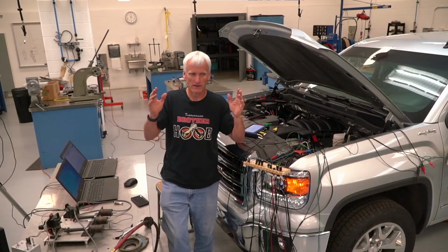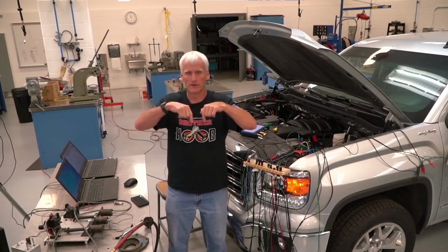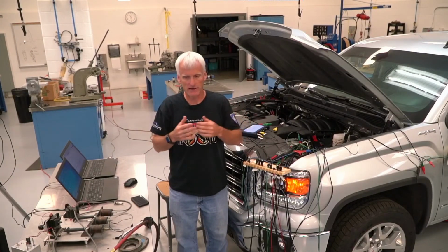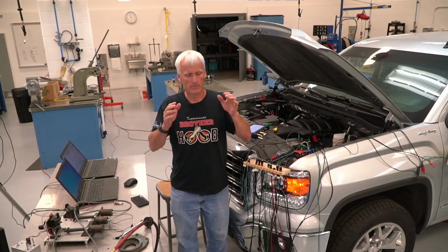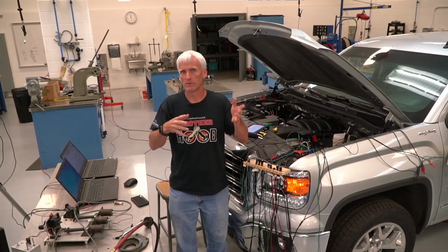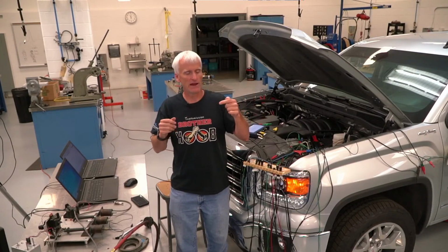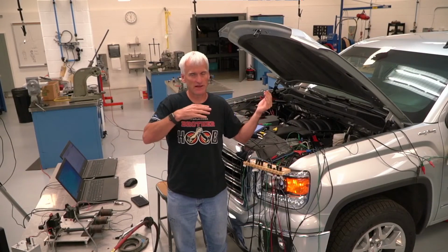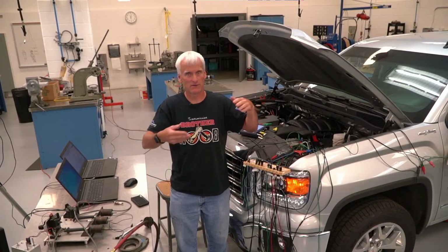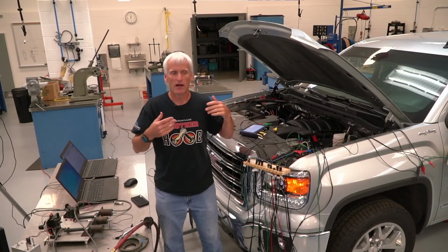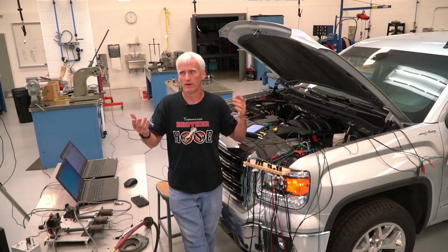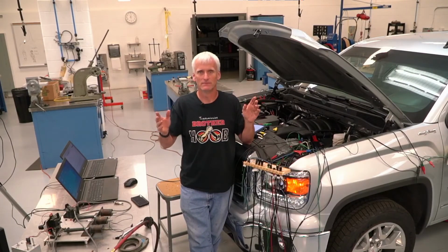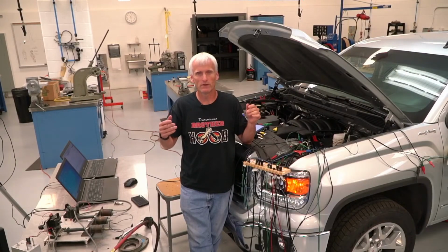And I figured, okay, with the heated O2 sensors, I had 2 of them in that were different part numbers, so that way I could just check to make sure that I didn't have just something weird going on. I was just checking the output voltage of it with them heated. And I pumped nitrogen in on one side. And using the theory of comparing oxygen on the outside and oxygen on the inside, and if there's a great difference, you should get a voltage, I should have gotten a volt, as much as I could out of it. But I got nothing. It was like millivolts, like 20 millivolts or something.